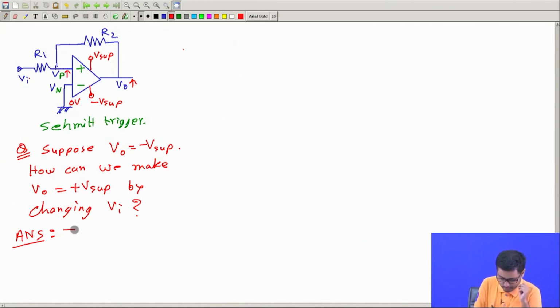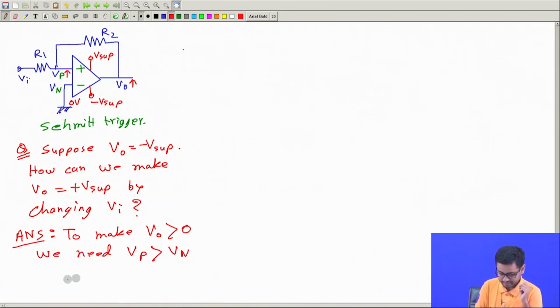So to make Vo greater than 0, we need Vp greater than Vn. So we have to increase Vp, right?